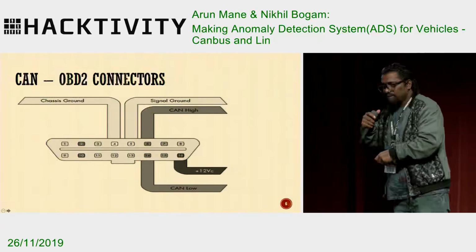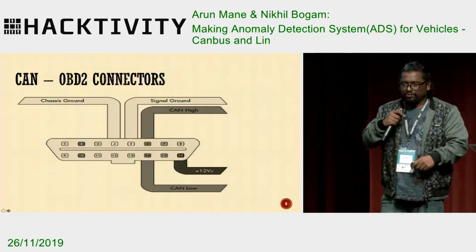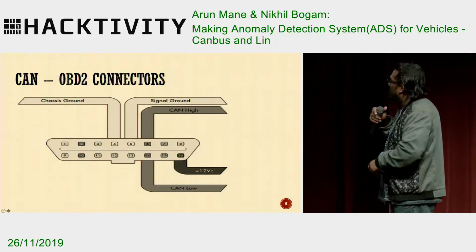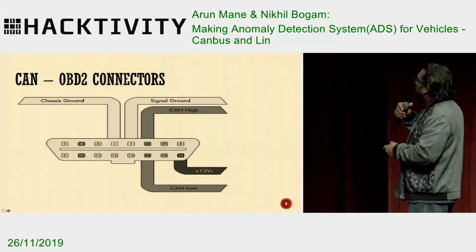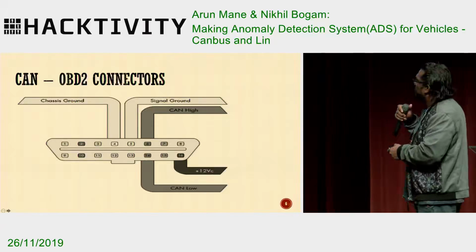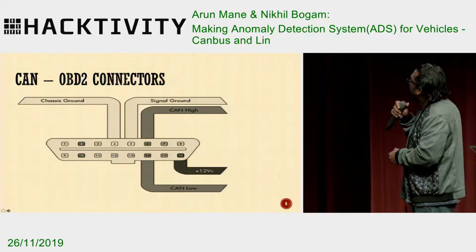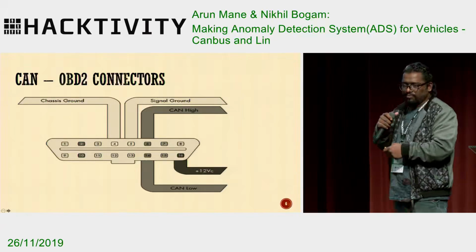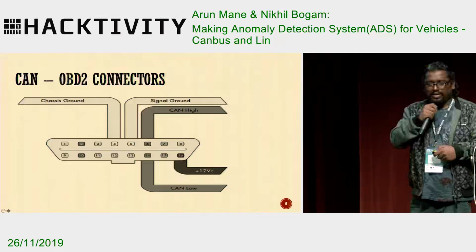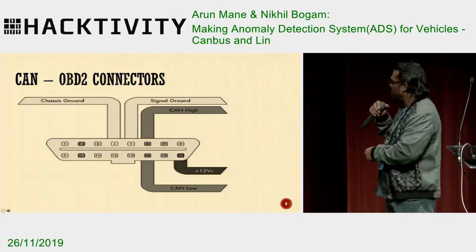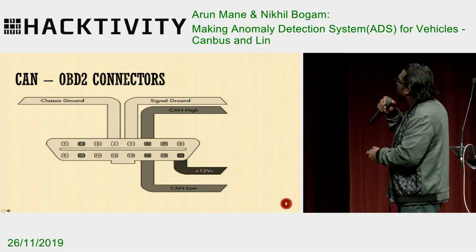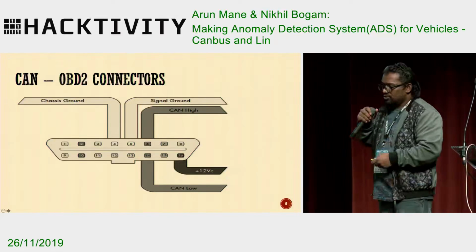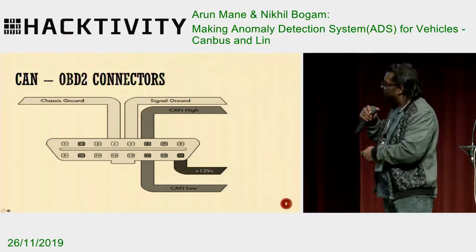So we are going to jump directly to OBD2. OBD2 is the onboard diagnostic connector. If you see here, pins 6 and 14 are CAN high and CAN low. So we are talking about the CAN bus protocol. And for the ground, they have chassis ground and signal ground. So this is the OBD2 port.